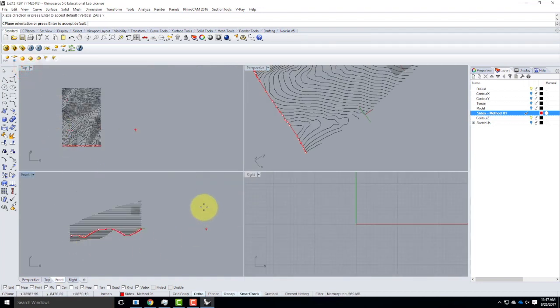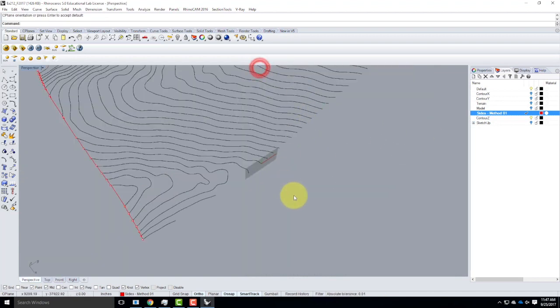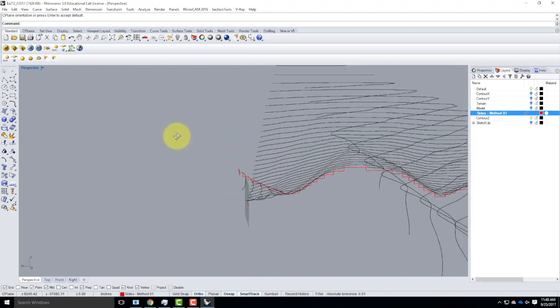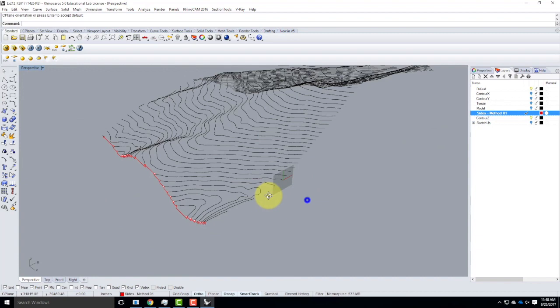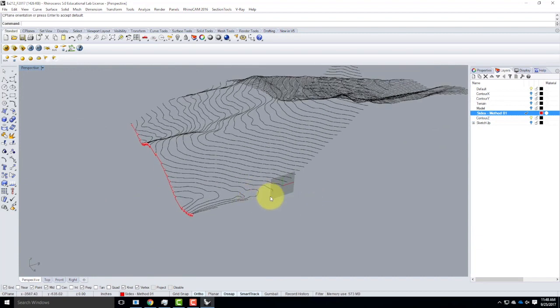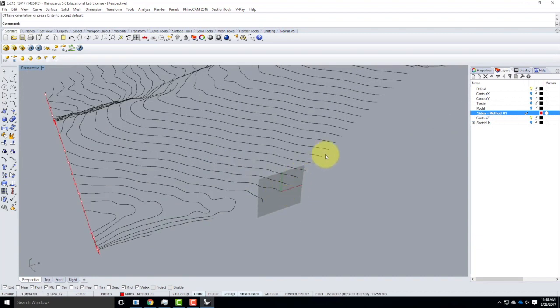So I'm going to move into one of the side views until I can snap and go up vertically. So there I am in a vertical direction. And once I click in the perspective view, you should now see the cplane vertical rather than horizontal. So when I've switched the drawing plane to be vertical, I can now start to draw right along this line without having to change anything. I don't have to do any rotate 3Ds.